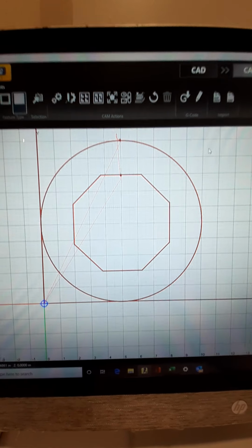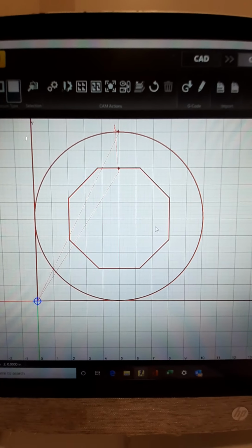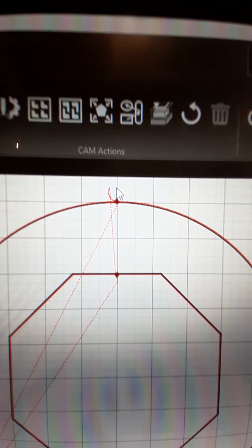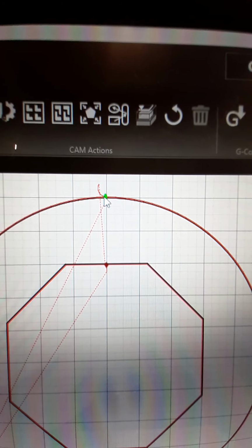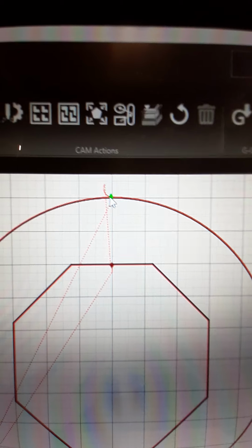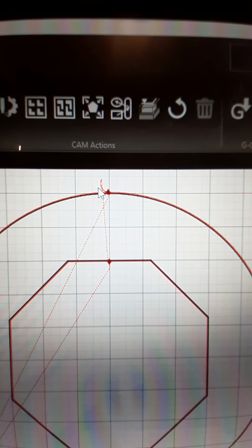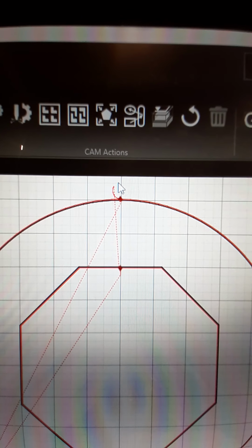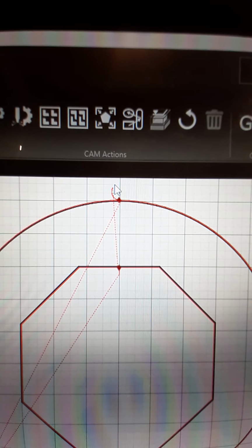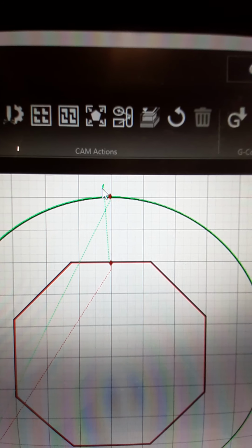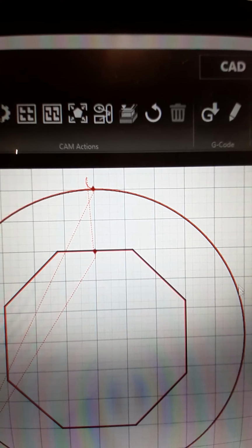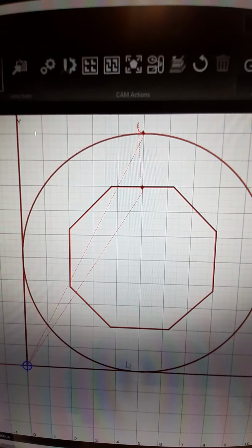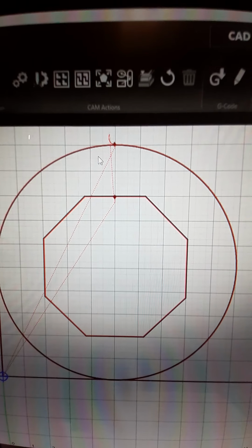Okay, see how this is going to be cut out. If you notice up here at the top, Anthony, you will see a semicircle cut. That's going to be a G02 command. And the reason that's in here is so the torch ignites outside the shape. It begins to make the contour. And that way it can cut the circle out in one continuous motion.